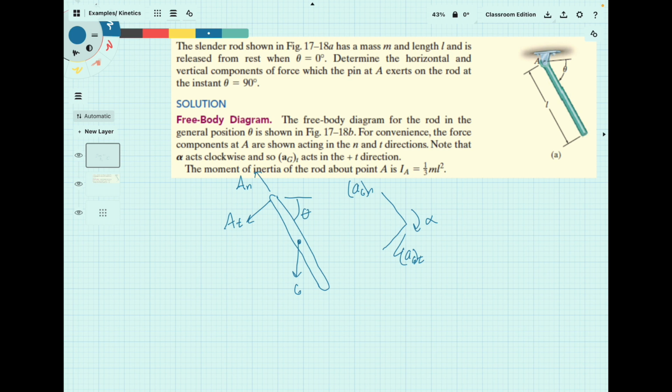So real quick, since it's going to rotate through angle theta, and the only inertial component acting on it would be the weight. That component of weight, as it reacts through theta, and we'll show this in a second, the component of weight that goes into, up here we can just call it the x and the y directions, is going to change as the bar rotates, of course. So it's not constant, is another way of putting it.